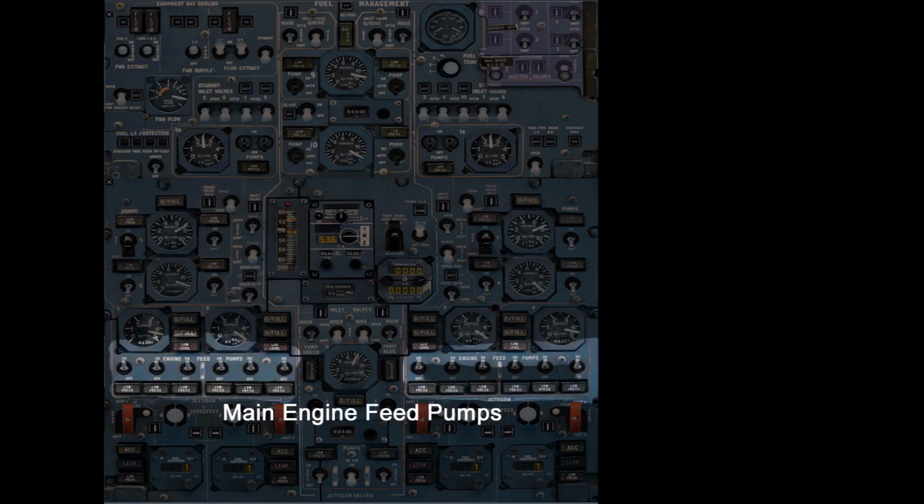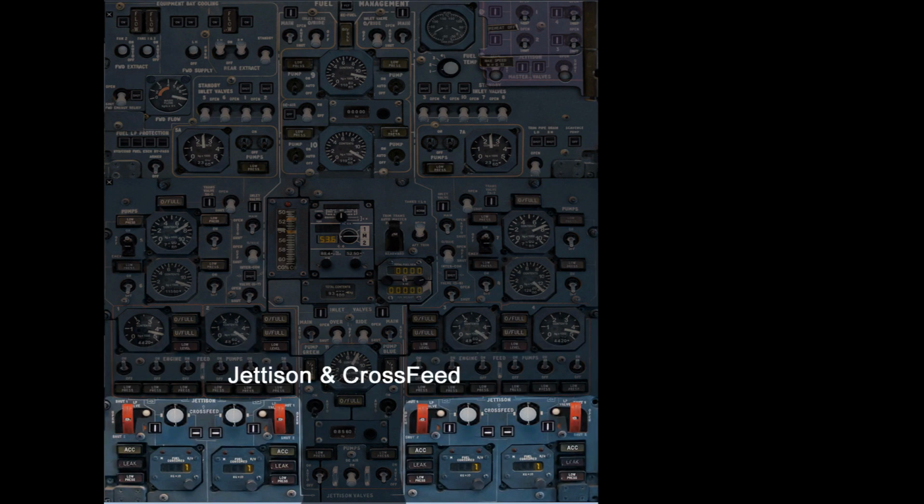At the bottom, below the gauges for the fuel amounts in the 4 collector tanks are the actual main feed pumps. There's actually 3 pumps, a main pump and 2 auxiliary pumps. And below that is the jettison and crossfeed system, which at this bottom panel, is rarely used, but it's important to know about.